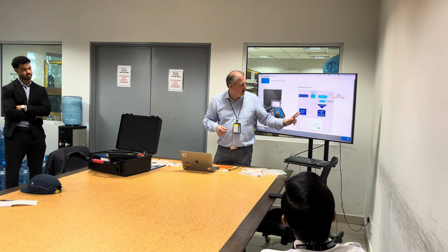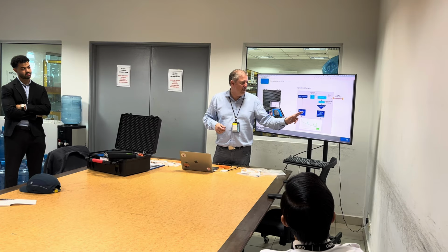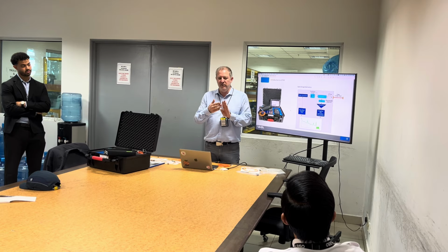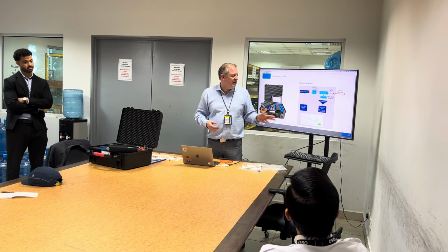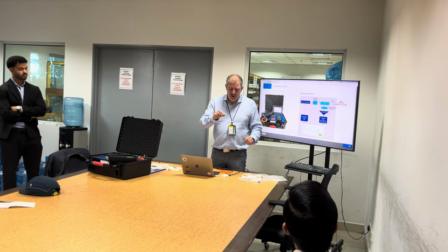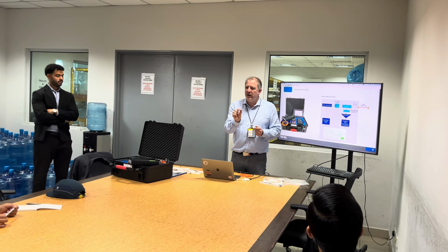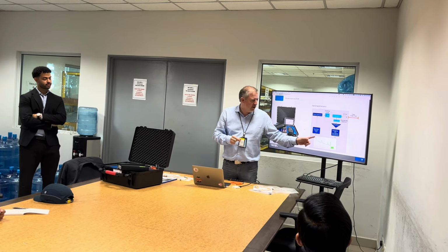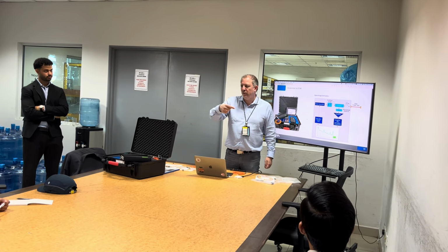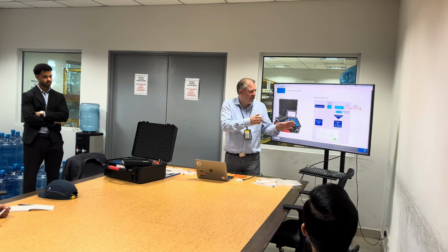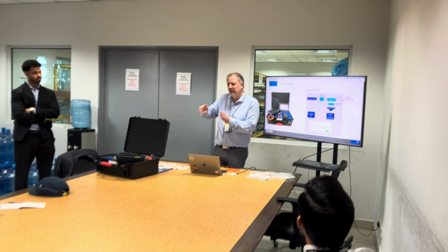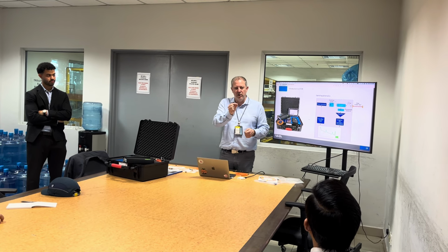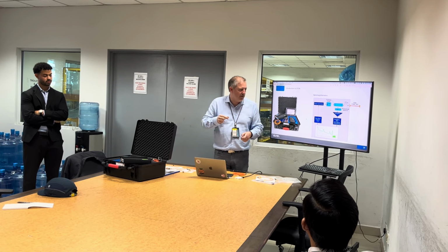Based on that, we control the time when we send the pulse and the time when we read what bounces back. So it's very fast because it goes at the speed of light. Then we send the pulse. We open the window for the photodiode that corresponds to one physical point on the fiber optic. We measure the level of light, and then we go to the next point. So it's like we were cutting small slices of the fiber optic, and every time we look at what part of light has been reflected in a small piece of optical fiber.